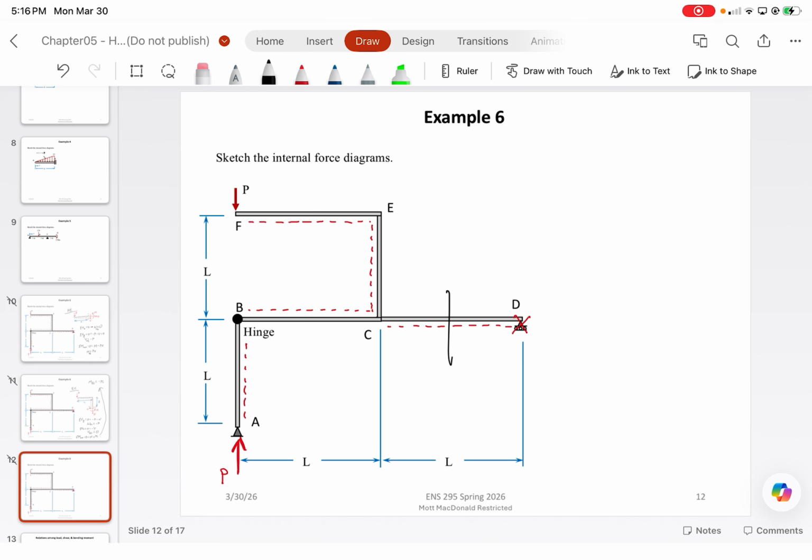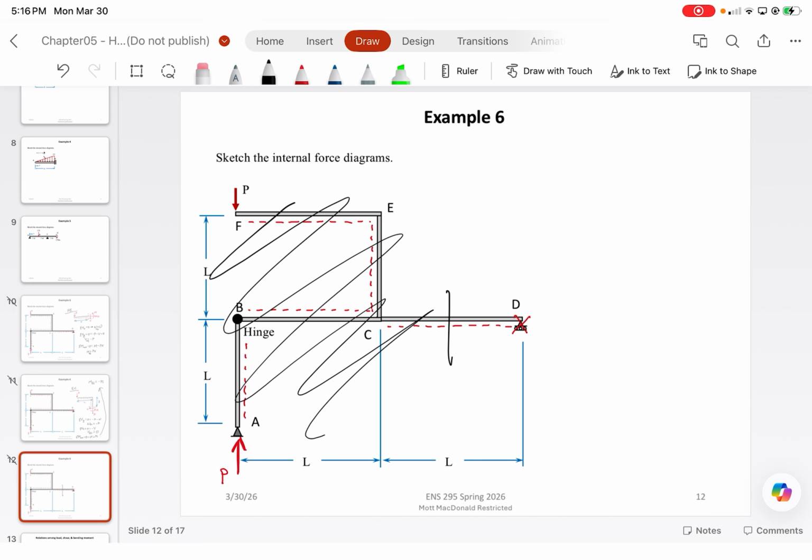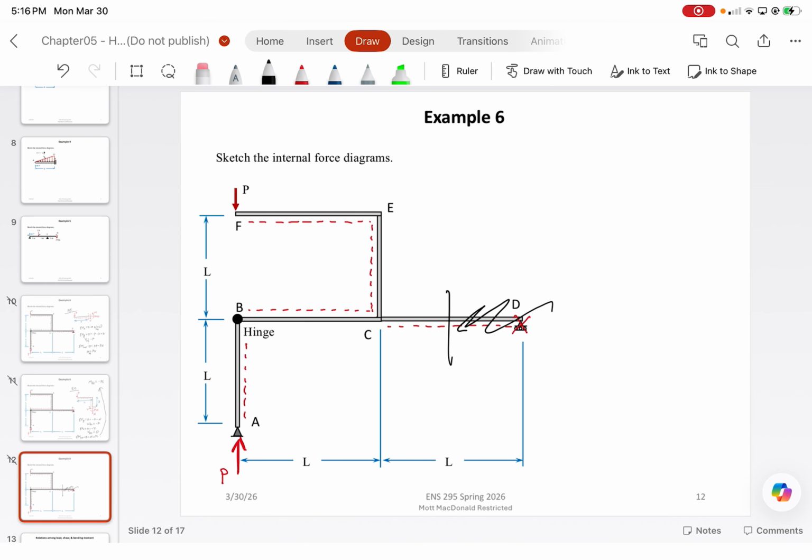We have our reference fiber. We have our cut. Our shear force for this sign convention is not as simple as down clockwise like the previous ones. What was the positive sign convention for a configuration like this? The shear force had to go up or down. It would go up since it's on the left, right? Exactly. And then which direction was the moment? It would be clockwise because it's always in tension to the fiber. Exactly. And then your axial force N.